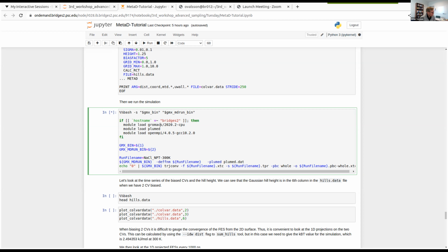Fluctuation dominated. I'm not totally sure what you mean by fluctuation dominated in the last question. Meaning, with the bias factor, as was already answered, people have used bias factor 100 in published results, and it is normally fine. It takes a bit longer to converge, but if bias factor 100 is needed to enhance the fluctuation enough to overcome the barriers, you will need to use that.